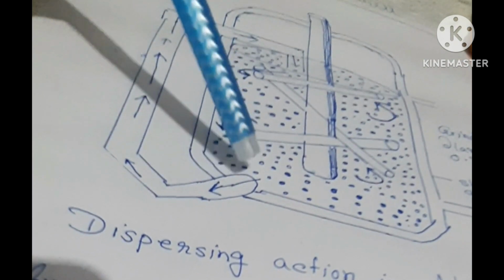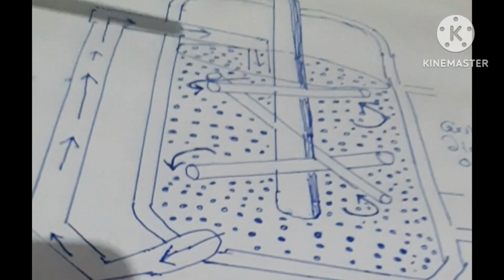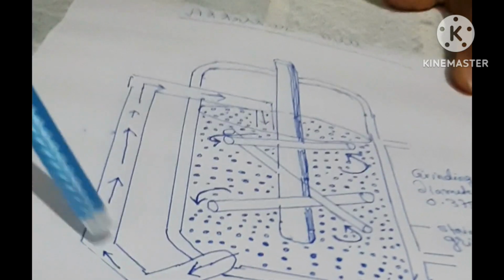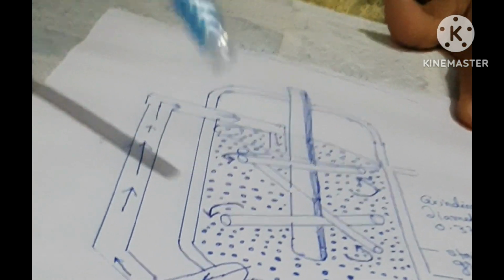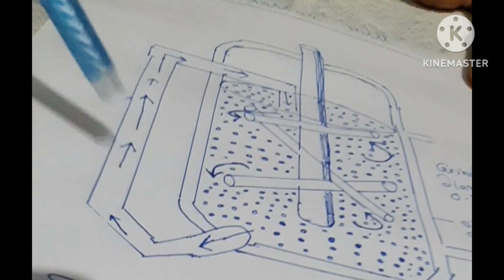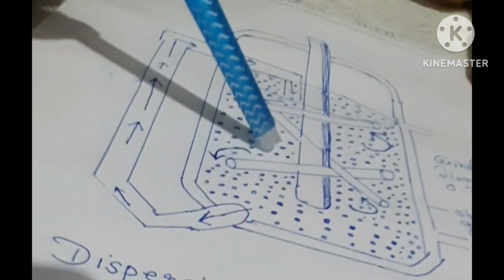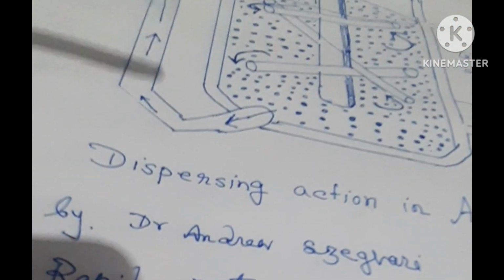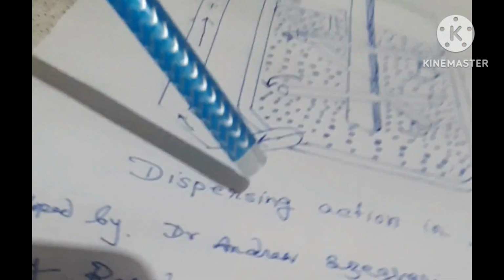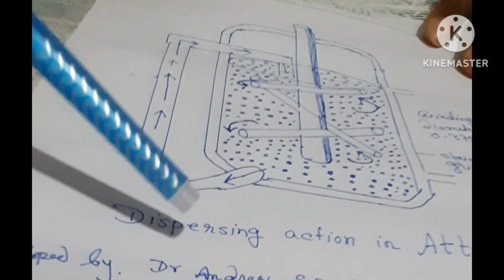The batch is pumped from the lower side of the attritor to the upper side, and after getting the fineness of grind, for finished paints a Hegman gauge reading of 7 plus is required. After proper dispersion and fineness of grind, it is tested on the Hegman gauge. Then it is unloaded, letdown is done, thinning is done, and tinting is done, and after tinting it is strained, filled and packaged.